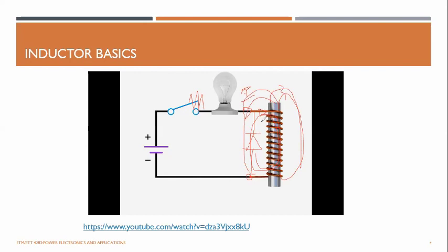While circulating through this diode, there is some power loss as heat, and there is resistance in the wires and everything. So the stored energy is dissipated, and these flux lines disappear over time. Otherwise, if there is no freewheeling diode, there will be a huge spark around this switch.